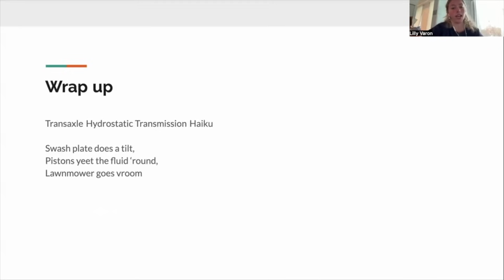In summary, the hydrostatic transmission behavior follows directly from mass conservation, momentum balance, and lubrication scale flow. By modeling the pump, motor, and leakage paths as interacting fluid mechanical control volumes, we obtain a fully predictive description of torque, speed, and efficiency.